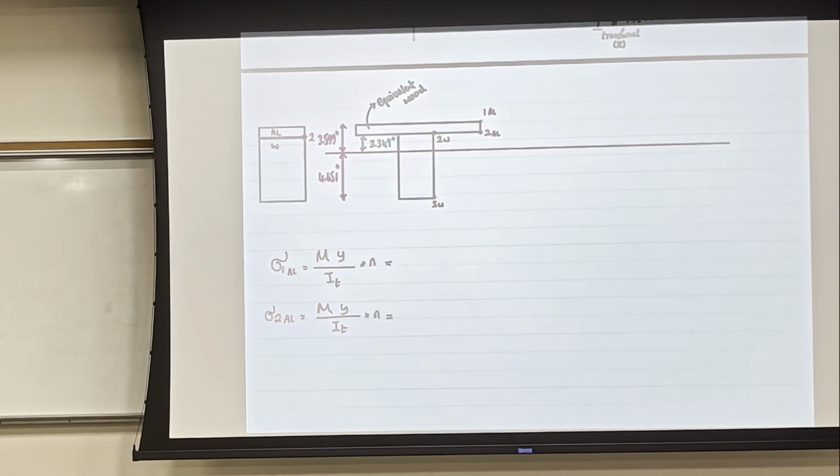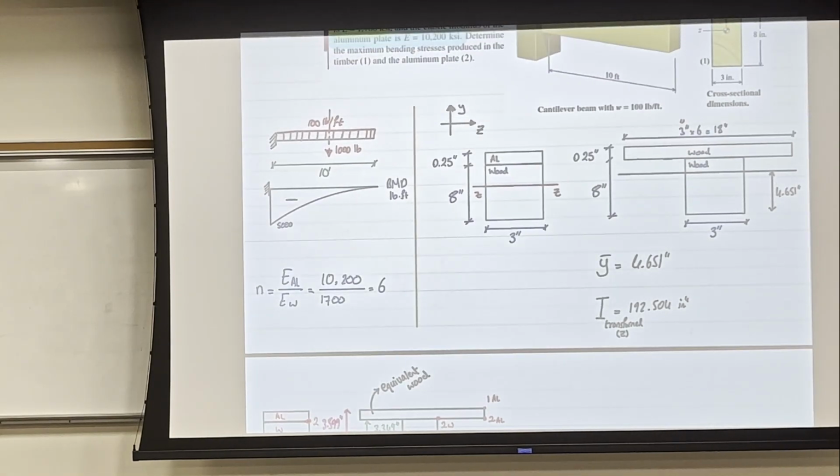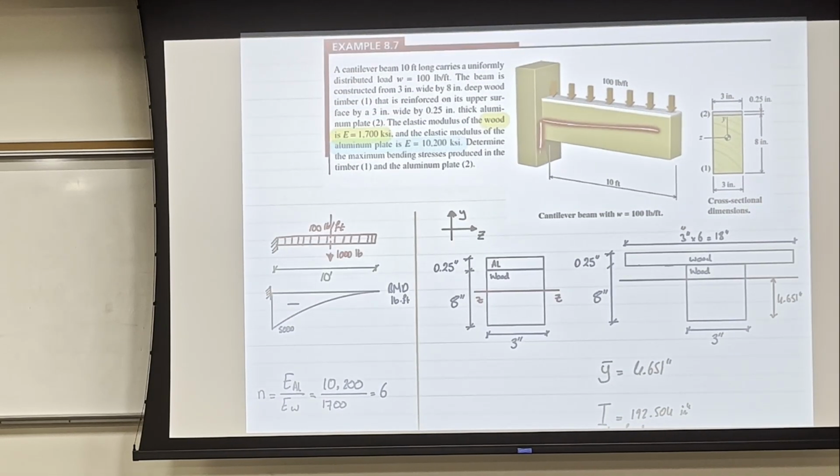So what was M? The moment here was down, which tells you the lower side of the beam. So if I have a beam like this, so this is the beam, the moment turned out to be down, and the moment tells you where the compression is. So the lower part of the beam here is in compression, okay? And if the lower part is in compression, we label this in 2D by having a moment line with an arrow looking down.